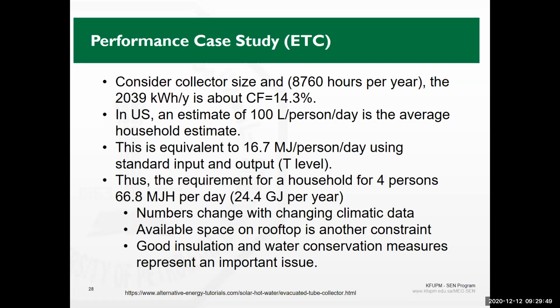When you are talking about efficiency, it's not a constant value. You cannot say that I have a solar collector that has 80% efficiency. You should say I have a collector that has this amount of efficiency at this temperature difference. You're right, yes. We will see the efficiency curves. You have efficiency versus delta T, or in many cases delta T over I, where I is the incident solar energy, and delta T is the temperature difference between the outlet of the collector and the inlet.